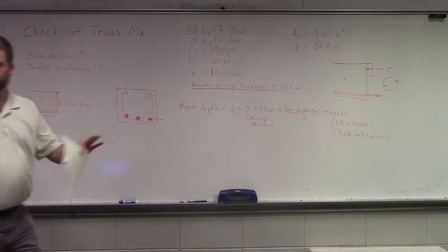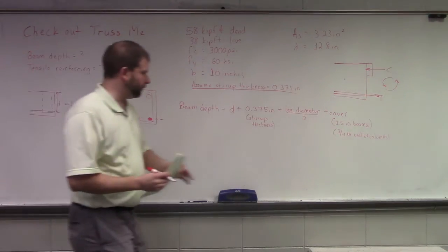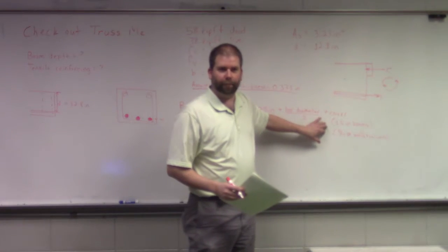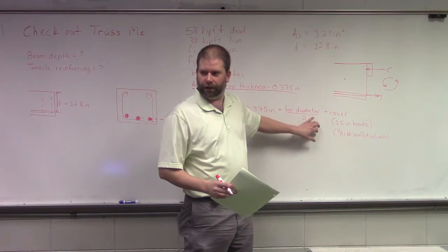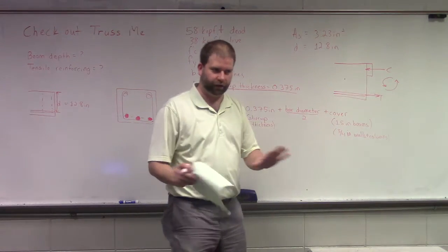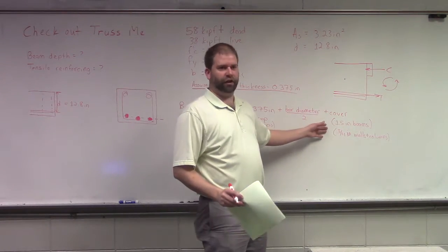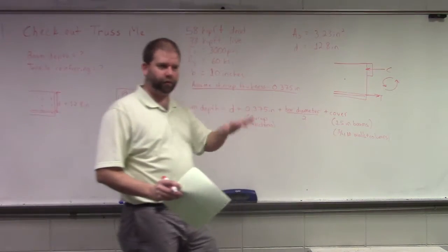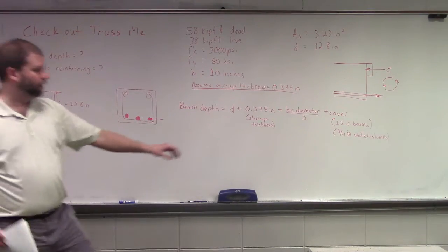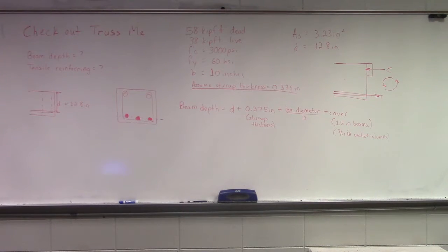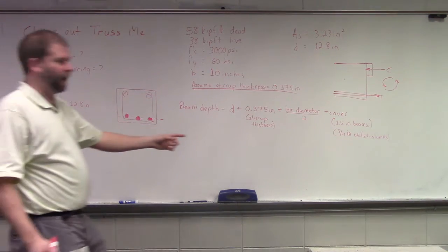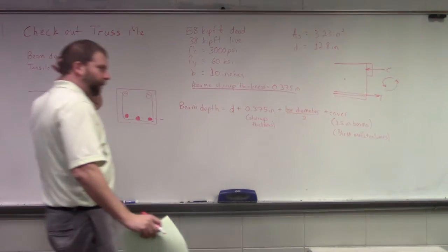And again, don't fall into the trap of thinking this is what we do all the time in industry. It's not the case all the time. Generally speaking, if we're doing basic, straightforward concrete design, 1.5 and 3/4 inch will be sufficient. But if we start talking about massive members, or really high strength concrete, we might have to start providing more cover, okay, to help support that weight.